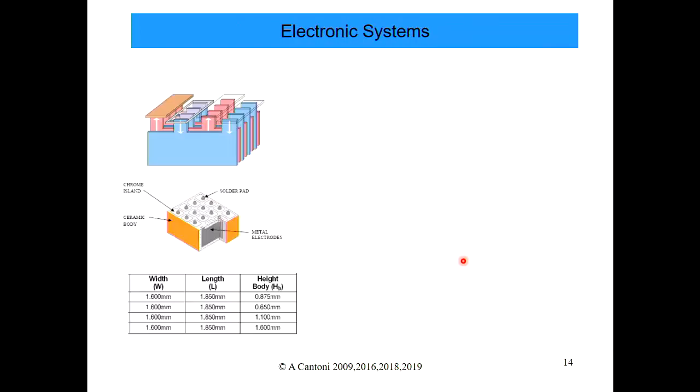So here's an example of another electronic system. It's a high frequency capacitor. Current travels through wires, and when a current travels through a wire, it sets up a magnetic field. That magnetic field generally can resist the flow of current, so it forms an inductor. At high frequencies, obviously inductors impede the flow of current. Capacitors designed for high frequency systems tend to have lots of plates in parallel with each other, so that all these inductances associated with the leads are in parallel, and the overall inductance goes down.